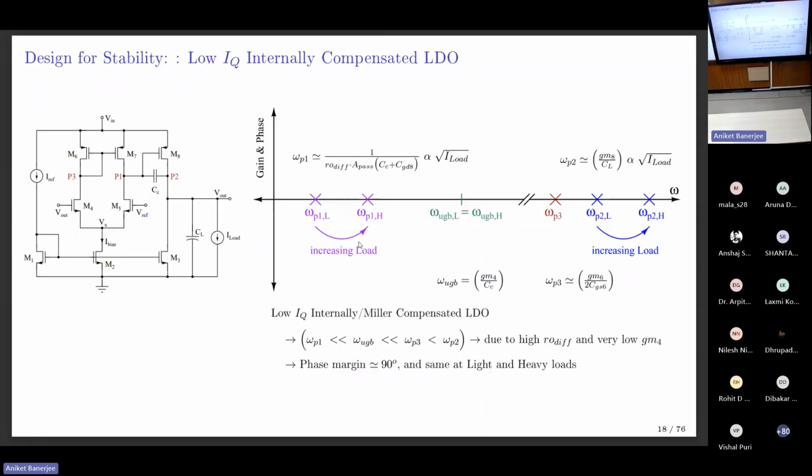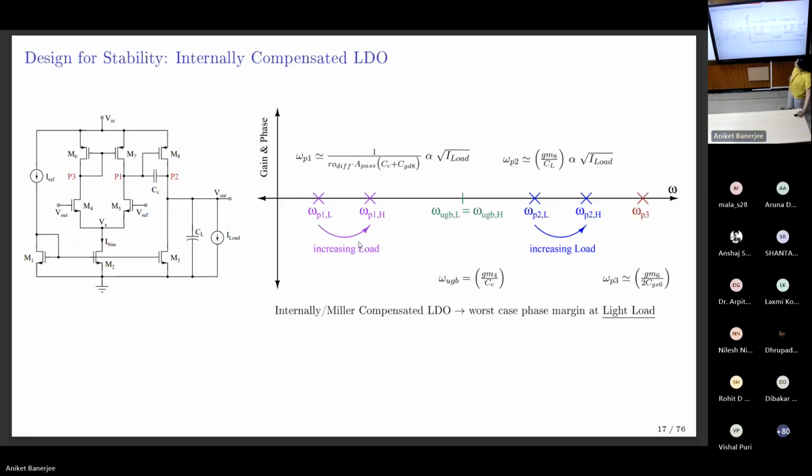And the last thing that I want to share before I hand over is why did we discuss stability analysis for a technology flow? The idea is, say I'm designing our FET using tech plots. I walked you through the process, right? You know your ID by W, your current, which FET is on ID, so you know the width of this FET.